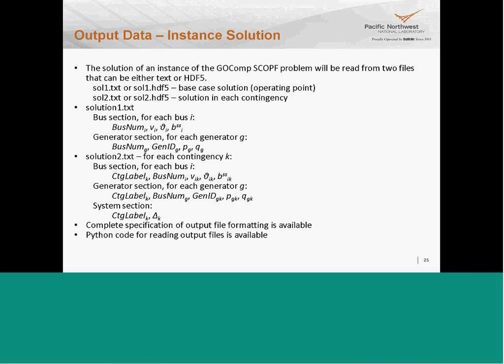A little bit of detail on the solution files themselves. In the solution file, you'll need to provide for each bus the voltage magnitude, voltage angle, and the susceptance of any switched shunts at that bus, total susceptance of all switched shunts at that bus. For each generator, you'll need to provide the real and reactive power outputs.